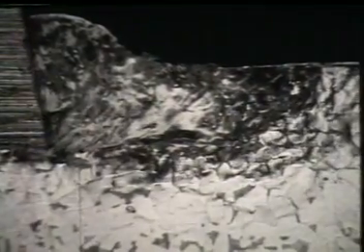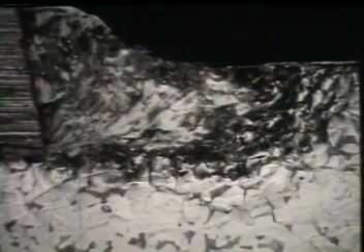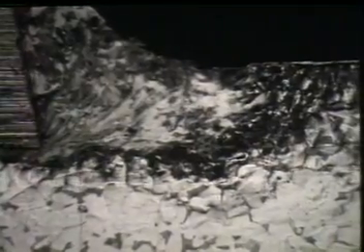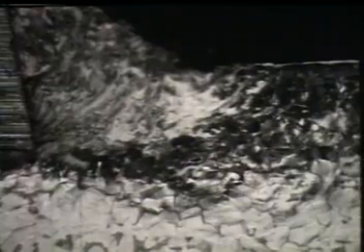As cutting continues, the dark band that indicates massive plastic deformation becomes more apparent. Note also the formation of slip lines beyond the dark band. To observe the bulk metal flow at the tool point, cutting at a lower magnification is necessary. This is a finer grained 1020 steel cut at a slower speed. Notice how the metal flows at the tool point.